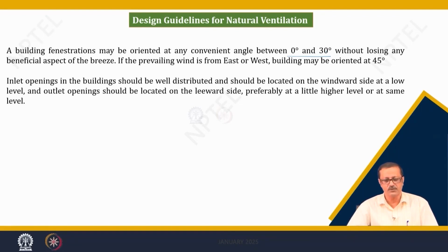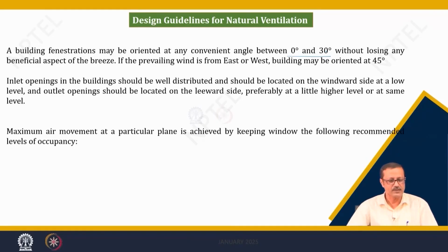Maybe the same amount of area, but well distributed, and the outlet opening should be located on the leeward side. Just now I discussed that we need to create a kind of pressure difference between the inlet and the outlet, otherwise there will not be much wind flow inside. The maximum air velocity at a particular plane is achieved by keeping to the following window recommendations.